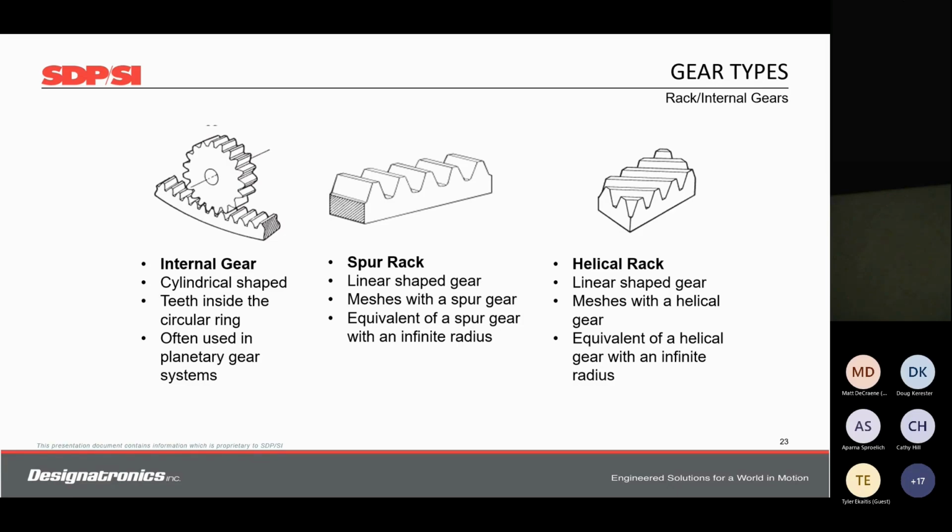One way to go around this and make it work is to either straighten the spur rack over the length, or cut it piece by piece, but make holes that are very accurate to the teeth of the gear. That's something that we specialize in, so that as you assemble this spur rack into your assembly, the spur rack bends itself as assembled, and that accuracy is maintained.